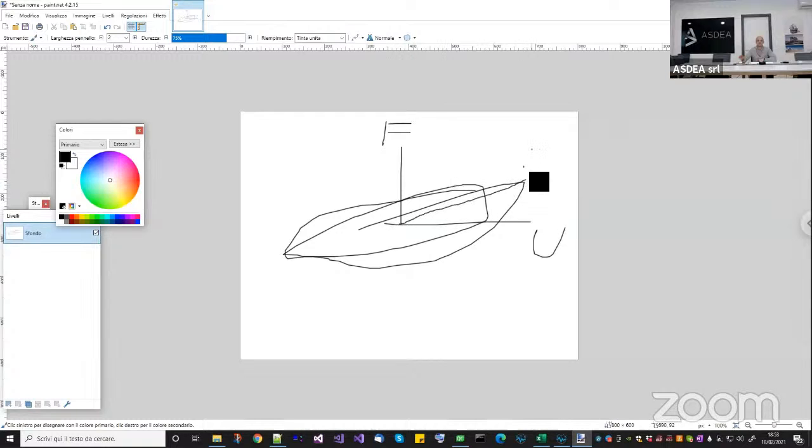I will reach a maximum displacement in positive direction and negative direction, and I will reach a maximum force in positive and negative direction. Then I grab the maximum of them. And then I compute the secant stiffness going from the center to the last node of my graph. This will give me an approximation of the equivalent stiffness of my isolator.